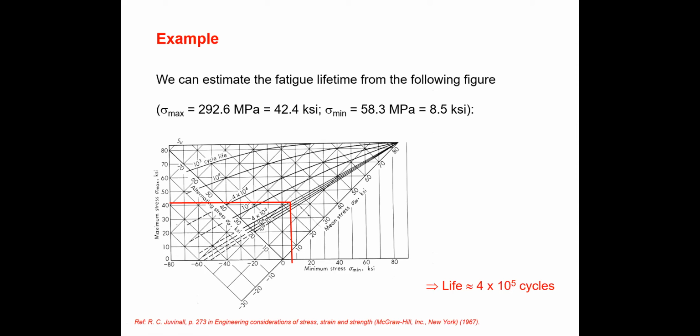So you can calculate the fatigue lifetime using this curve I told you. With this example, I will explain. The maximum value we already know now, but you can't use this graph with megapascal. You need to convert to KSI. Normally, if they provide the relation between megapascal and KSI, don't worry.